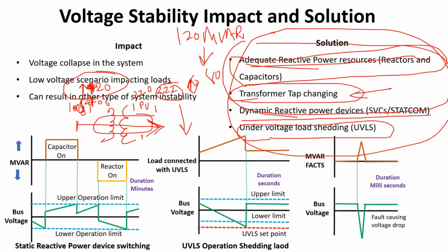Another thing is that for reactive power, you have to schedule the generator also. We do scheduling for active power, but we don't do any scheduling for reactive power. So you are also facing the same issue. When you go to a generator facing high voltages and ask them to absorb reactive power, they will tell you a lot of stories, that these are the issues that I am facing.